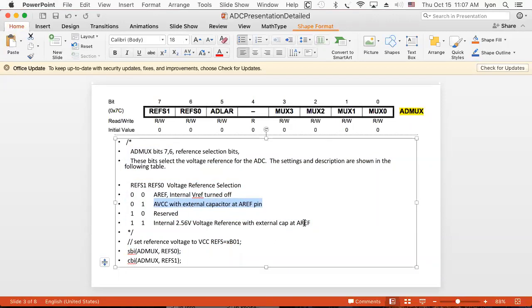And that's convenient because we always have power, but it's inconvenient in another sense, because if the power supply fluctuates just a little from 5.2 down to 4.8, it's going to throw off the whole ADC converter. And if our sensors output analog voltages or current, then it's going to throw off all our sensors too. So inaccuracy in something like a thermocouple will show up with an extraordinarily high variance in temperature. So if you have a need to have precision, this is not a good way to go unless you can be sure that you have a precise VCC. And we're never really that sure of our VCC.